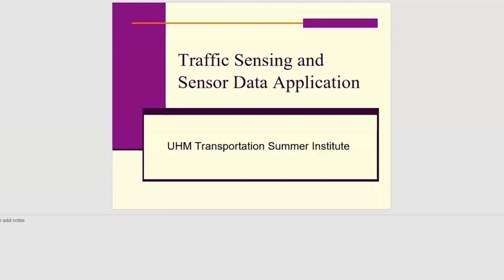Here is a very typical intersection. We have traffic from different approaches. You can see the signal head. It shows green, red, yellow, and allocates the right of way to the different approaches based on, ideally, real-time detection information. You see the pavement cut. Those are what we call inductance loop sensors. When a vehicle arrives at the intersection, the vehicle arrival triggers signals captured by those loop detectors, and the loop detector will send the data.